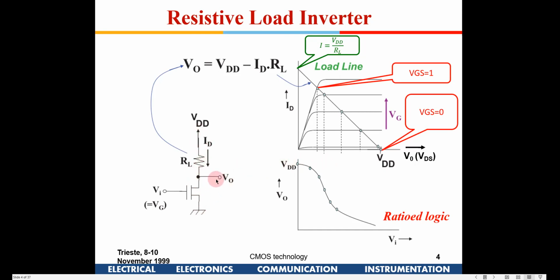So now if you see here, for this nMOS out here, V0 is nothing but VDS and Vin is nothing but VGS. So I plot those curves, right? So the characteristics would be the nMOS transfer characteristics. This is known as nMOS output characteristics, VDS versus ID characteristics for various VGS. So these lines which are going like this are only the nMOS characteristics.